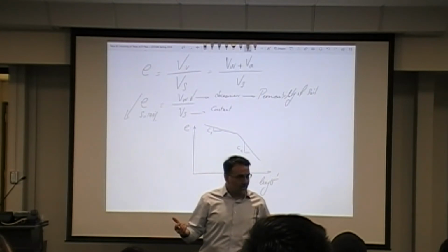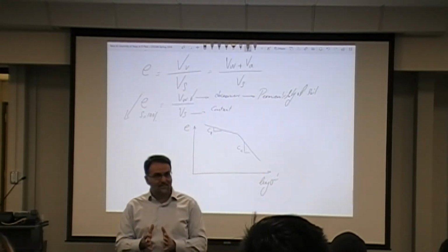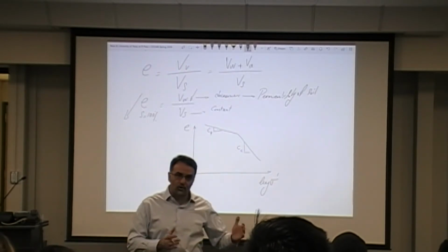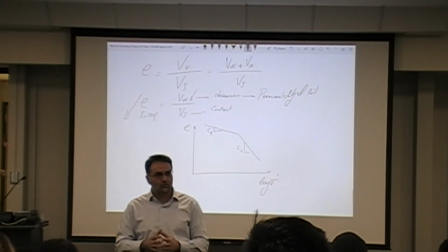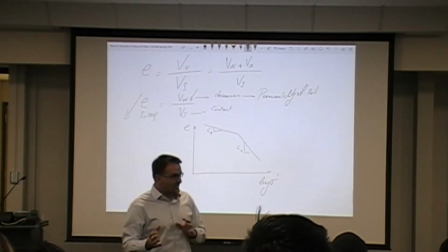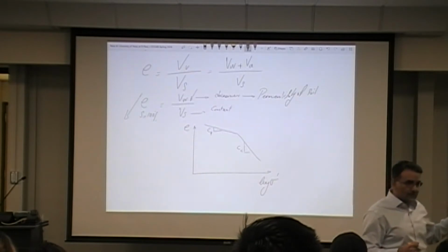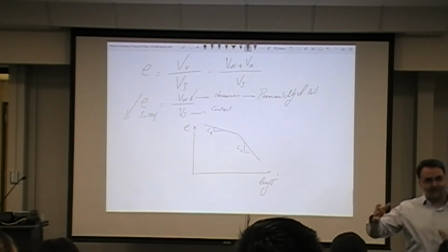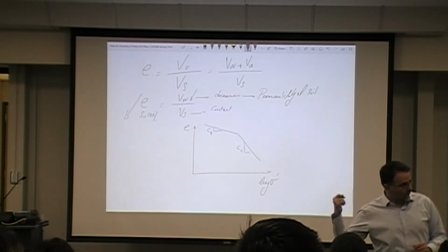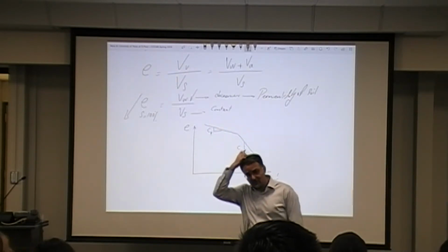We know that the drainage is different in different types of soil. We have clay material that takes a whole lot longer for drainage to take place as opposed to a coarse-grained material with big chunks of gaps in between, right? So that's basically the distinction between the two. We don't have the permeability right in here, but we are going to look at the after effect of that in the plot here. So how do we develop this plot? Based on a one-dimensional consolidation test.